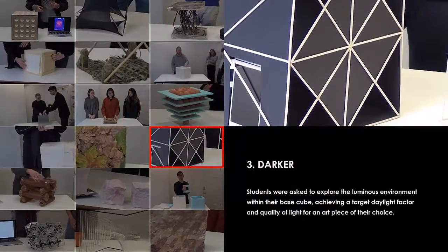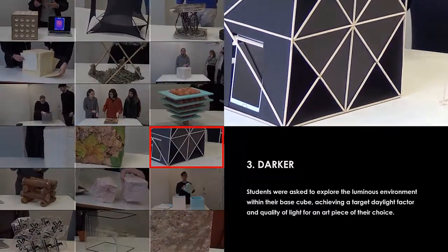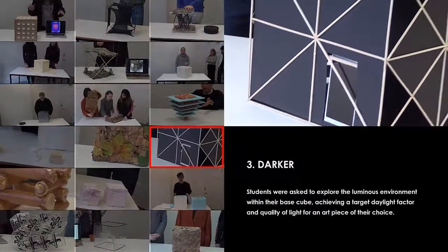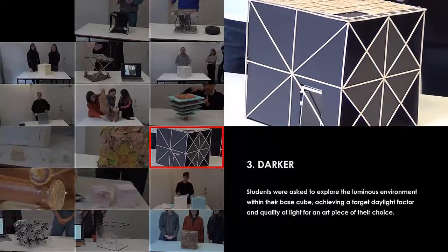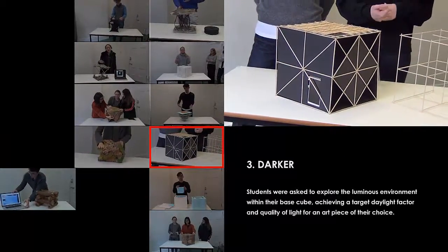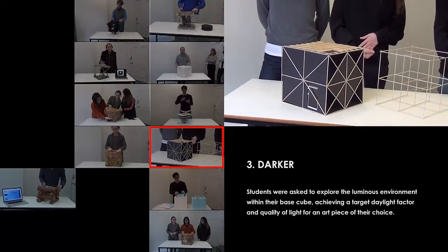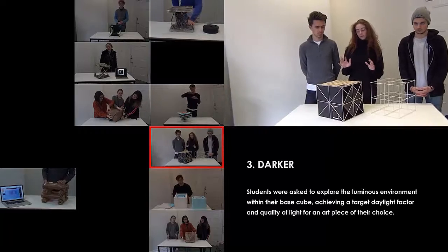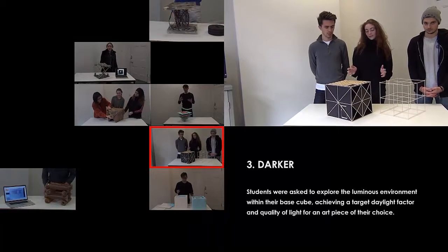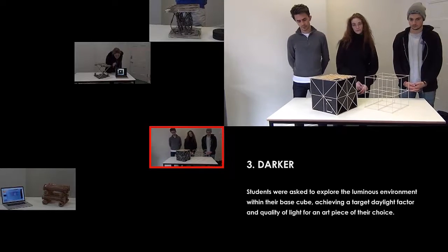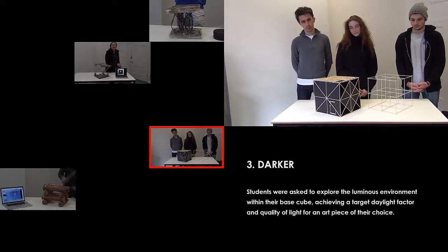So we inspired our design from Japanese cranes, and to create a dynamic light movement, we used the pulley weights aligned. So when the light moves over it, it creates a mashrabiya effect, like in Arabic architecture. And so we had several tests. One was only with a dark cover, and it was too dark, so we changed, and the daylight factor was reduced to 2%.